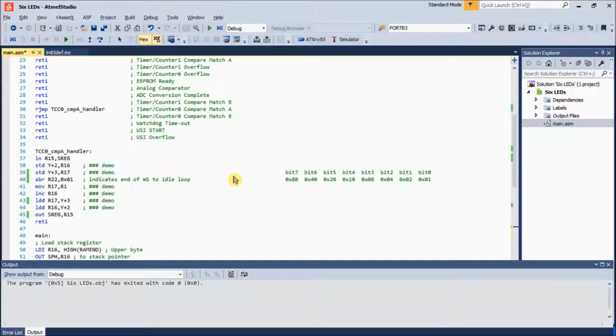The way that the definitions are done in the definition file, they talk about bit numbers. That's why they always have a 1 left shifted by, for example, bit 7. Bit 7 is not actually a defined value in there, but I'm just referring to this. It would also be possible to define them as, instead of being a 7, could be an 80, and then you wouldn't need to do this one shifted. But I'm afraid that's the way that they've done it.